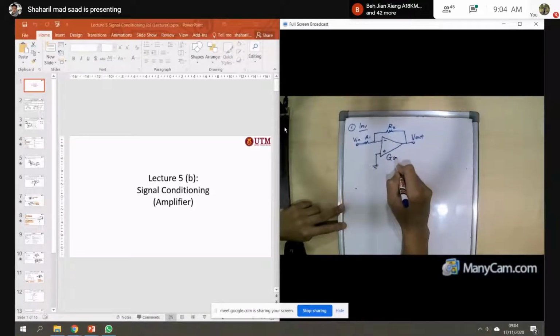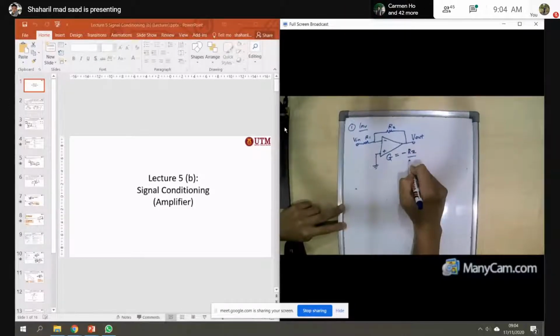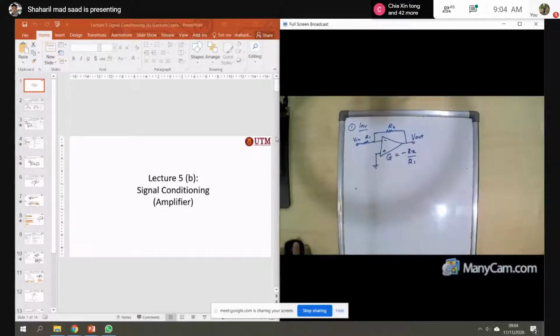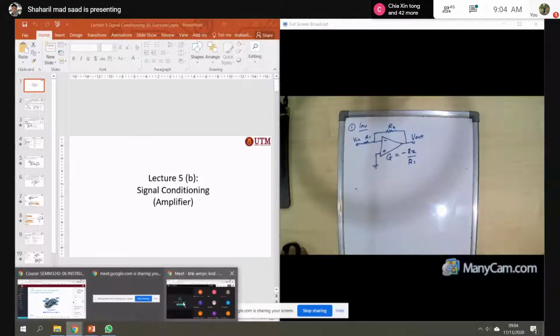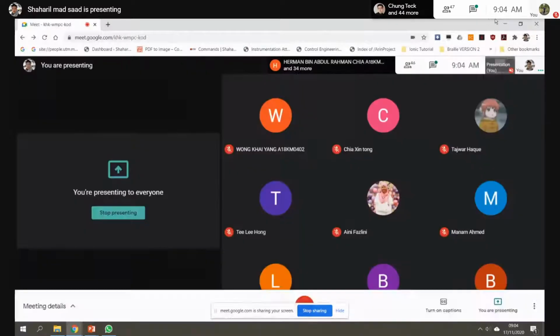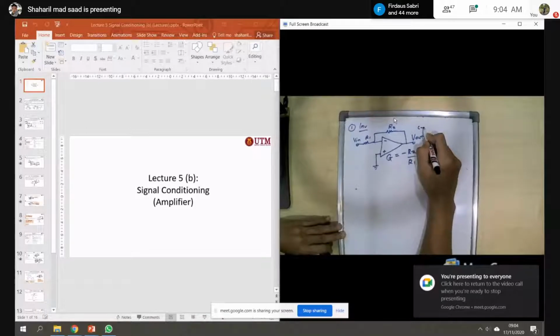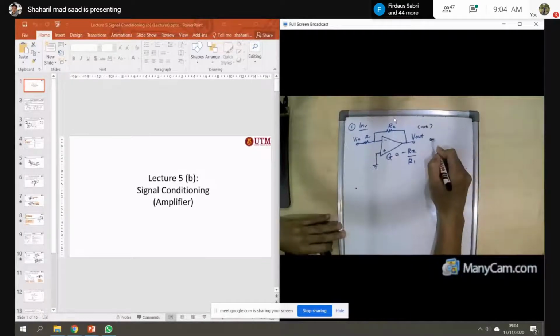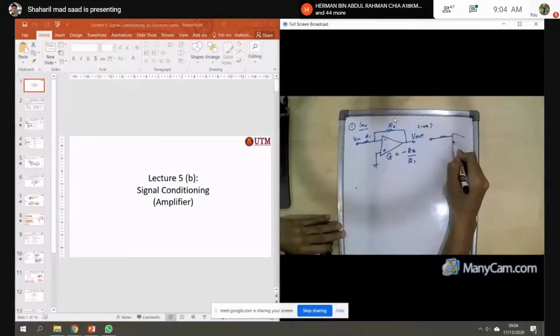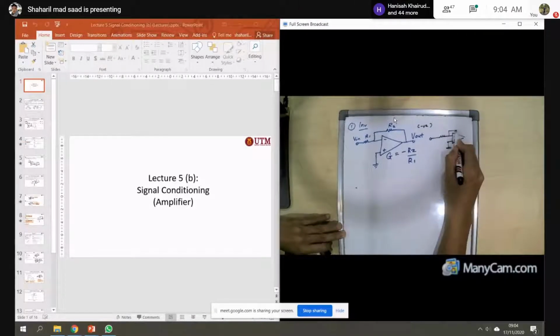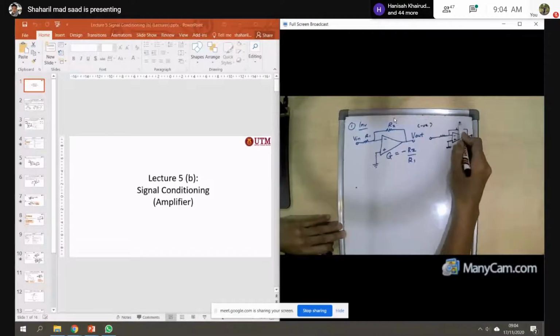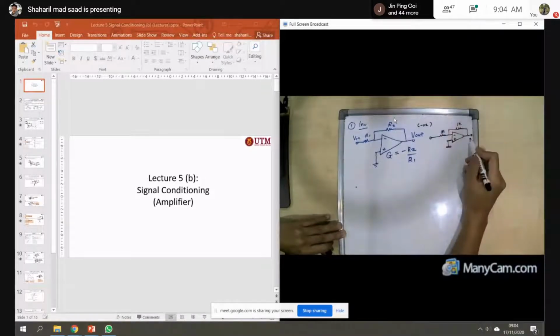Now the gain here, I call it G, is equal to minus R2 over R1. Because of the inverting, it inverts the value of the input, and then you get negative 1. You need another inverting stage in order to get a positive output. Maybe you can choose 1k and 1k; it must be the same value. This one will be your final output, the out.